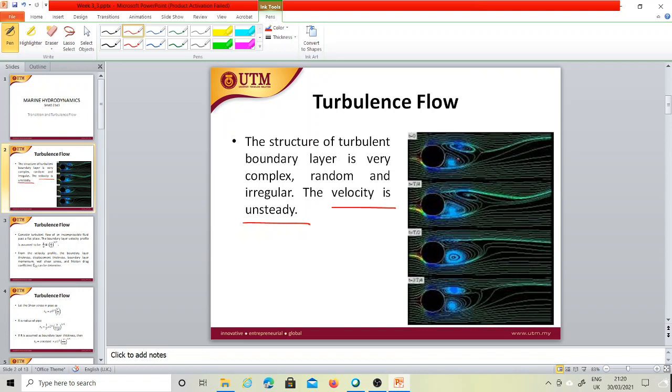Okay, so this is just an experience from the wind tunnel. If you have the cylinder or any spherical shape, then beyond it, as you know, at this point the separation will occur, right? So I already explained the things in my last video, how the pressure changes and how the velocity changes. So at this point you will have zero velocity. It means the flow will separate from the body, and after that there will be negative pressure, right? So due to that negative pressure, there will be some space where we will have a vortex. Okay, so we will have the eddy, so it will circulate the motion at this point.